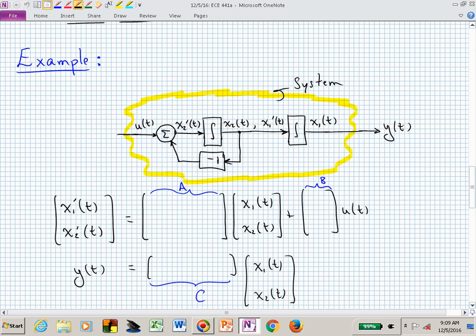What's in the first row of the A matrix? Or what's in the 1, 1 entry of the A matrix? x1 prime is really just x sub 2, isn't it? No direct input, no variable x sub 1 coming in to create it, so the top row we can actually complete in that way.